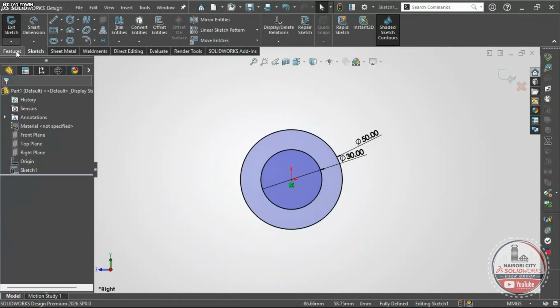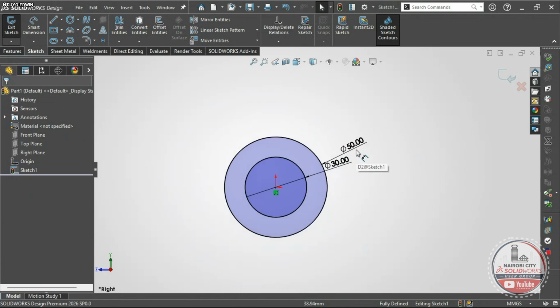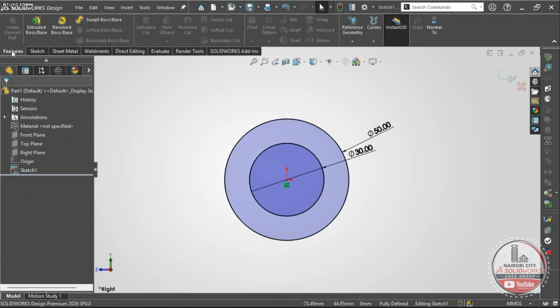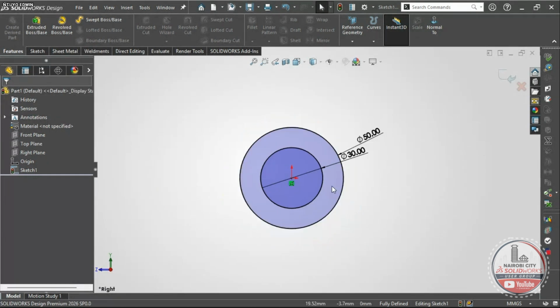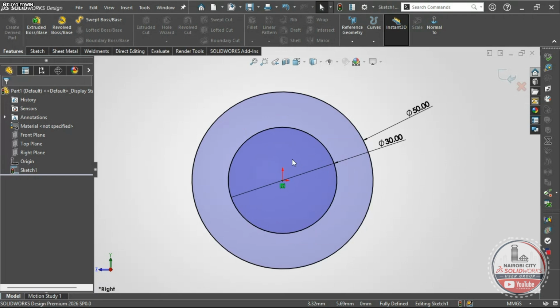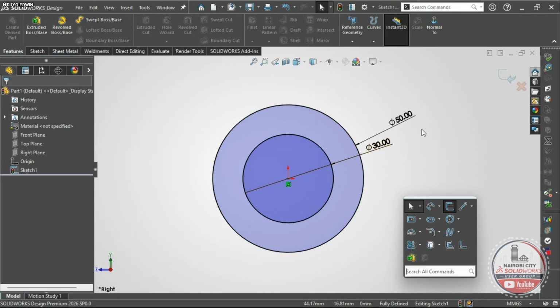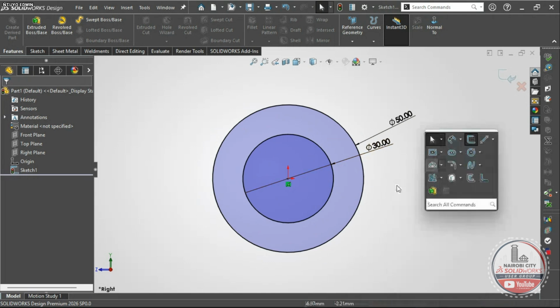So I'm going to extrude. For extruding, there is an option of going to sketches and then tapping on extrude. However, in my point of view, that is kind of more time consuming. I'll just tap S on my keyboard. When you tap S, these are shortcuts. You find that most of the shortcuts in here and the commands are going to be for sketch.